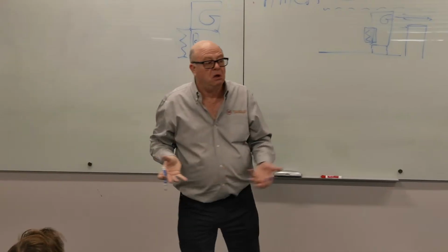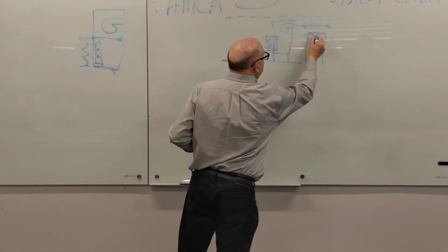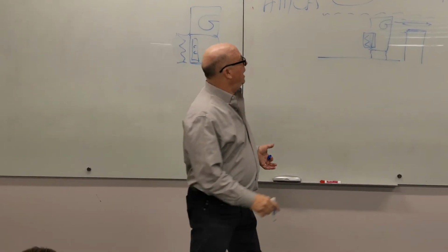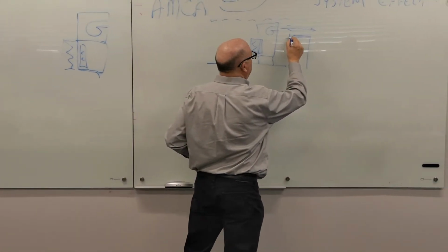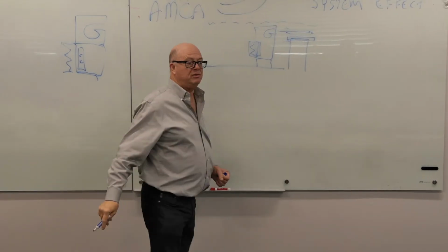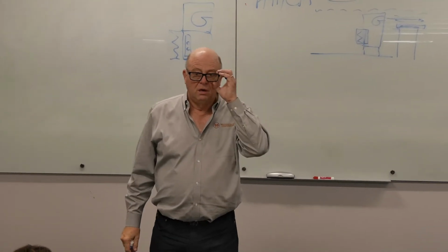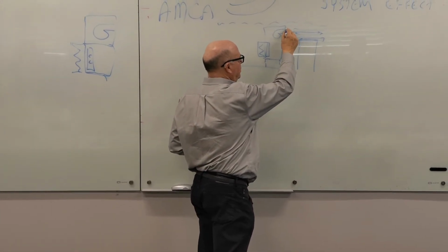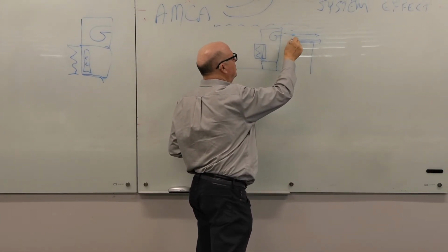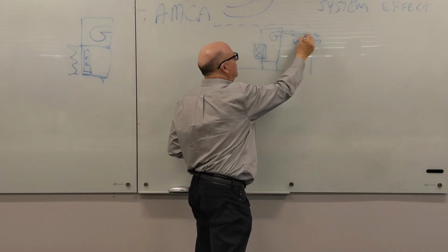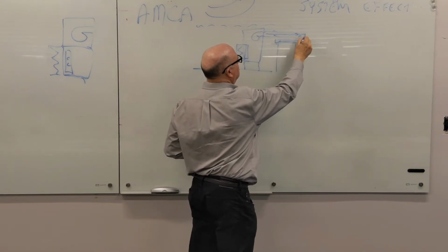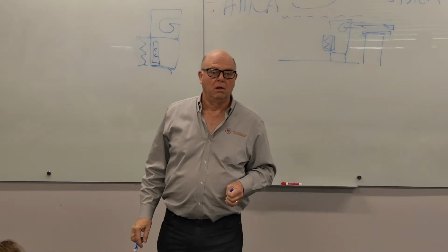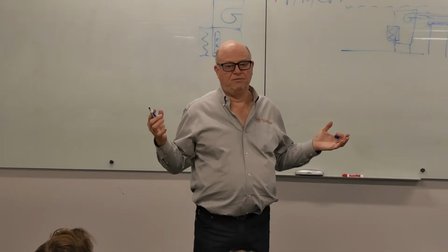you could. And then on top of that, you've built the tunnel so that it helps you too. And if you were really sensitive to it, you'd put some sound absorbent stuff across the top here. You also obviously did not use wrapped, you'd use lined typically till you got the other side of the corridor. I mean, that could be 10 feet, it could be 15.